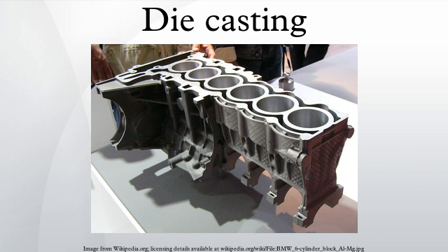Type metal, an alloy of lead, tin and antimony, is used for casting handset type in letterpress printing and hot foil blocking. Traditionally cast in hand jerk molds, now predominantly die cast after the industrialization of the type foundries. Around 1900 the slug casting machines came onto the market and added further automation, with sometimes dozens of casting machines at one newspaper office.